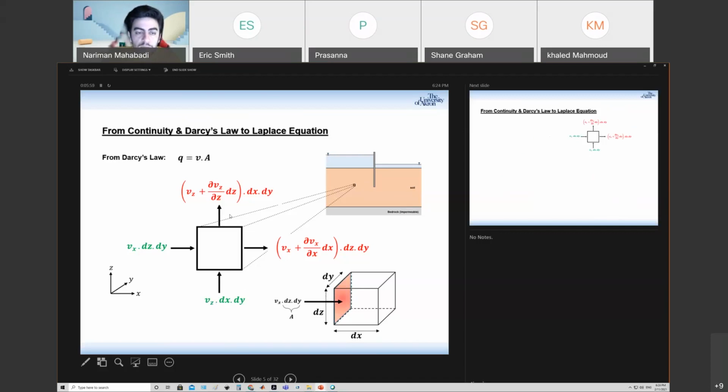But what about the flow out? We're going to have some change because of the change in the velocity. This is about the energy dissipation in your system, right? Energy dissipation or adding energy, depending on which point we are moving from to the other point. But this is all about the seepage problem, right? We have some permeable system, it has some conductivity or permeability, and we're going to lose some energy through this movement of fluid.